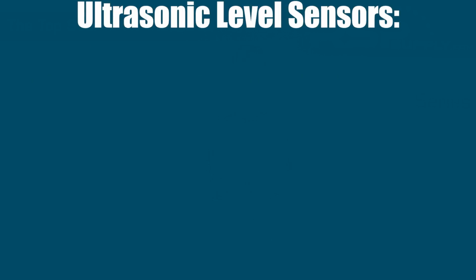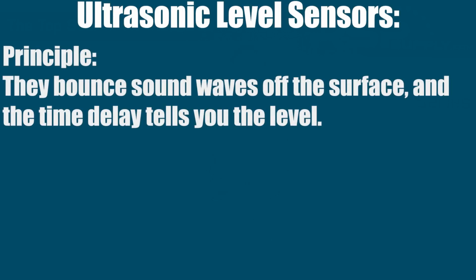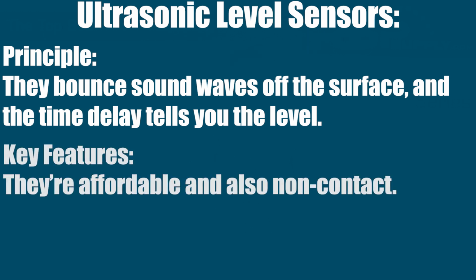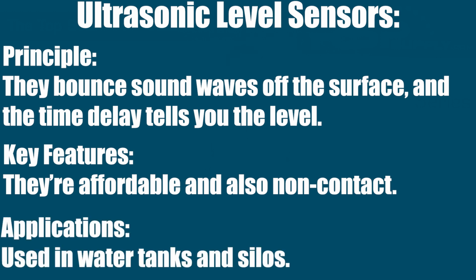Then there's the ultrasonic level sensors. They bounce sound waves off the surface, and the time delay tells you the level. Some key features of this are they're affordable and they're also non-contact. Used a lot in water tanks and silos.